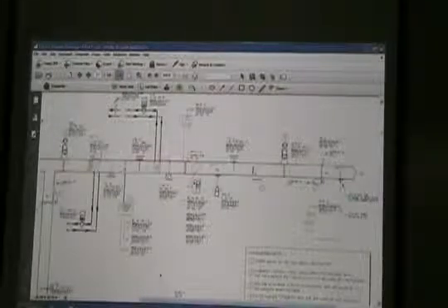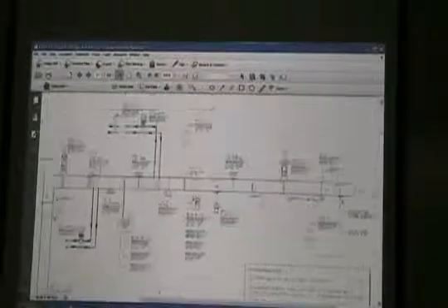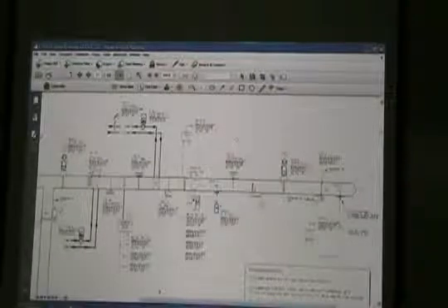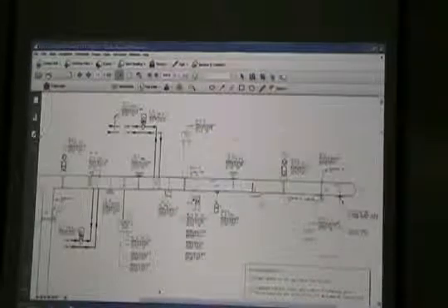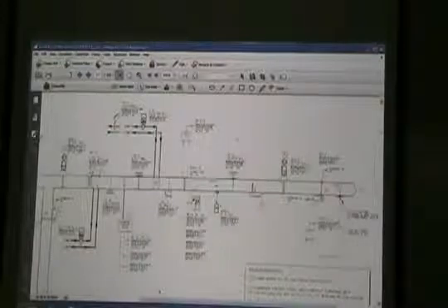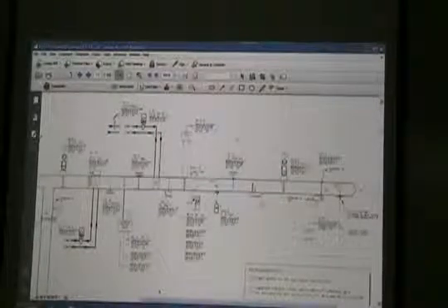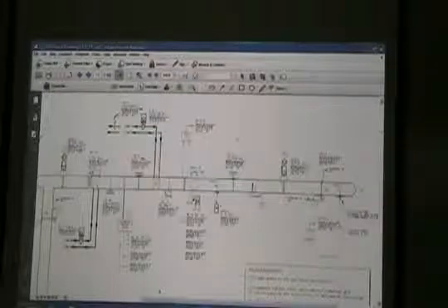Okay, so this is about where we stopped last week, or Tuesday, and we're going to go into the chill water valve. There's the chill water coil, there's the chill water valve. You can see we've got a point labeled there for an analog output. We've got a temperature sensor here that's just monitoring chill water return temperature, and we'll look at the sequence to see if that has any bearing. And that would be an analog input into our controller.